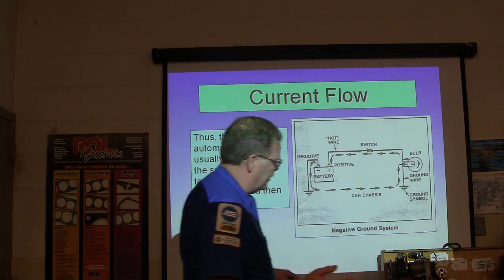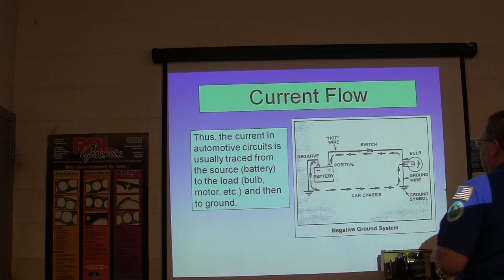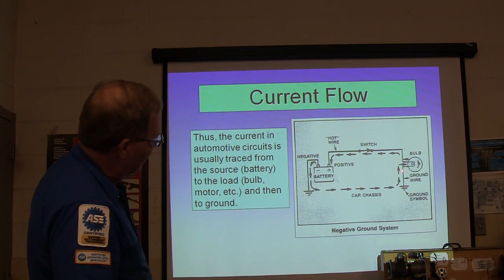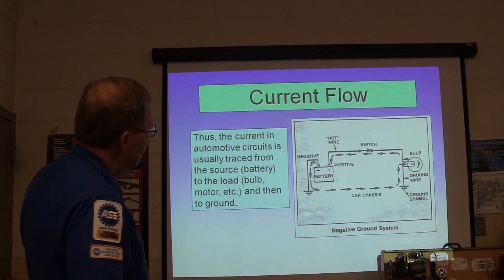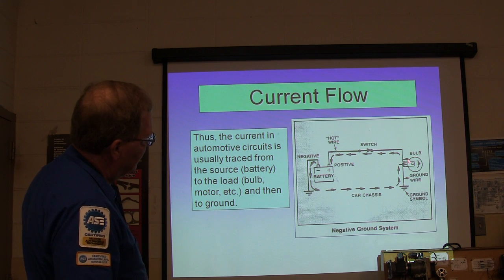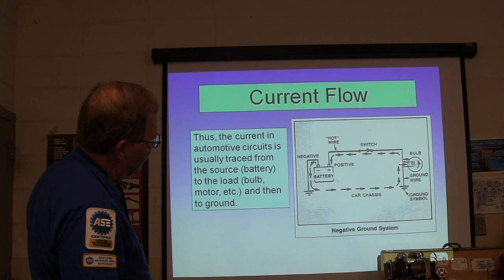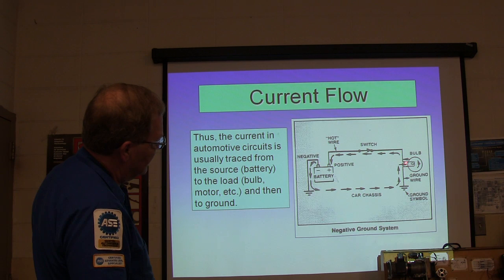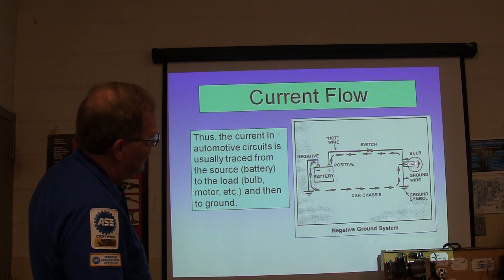Anyway, if I'm going to do this, I'm going to take my test light and hook it up over here, and I'm basically going to start right here, and see if I can get power right there. Now you can hook it up, if you can measure from here to here, that's perfect, because you're measuring all of this automatically, and you're seeing the ground too. So if I got power and ground at my light, then I know I got a problem.